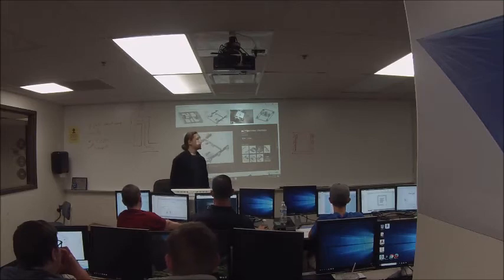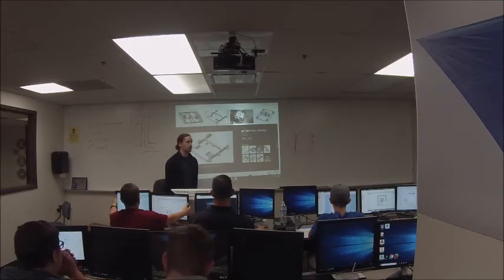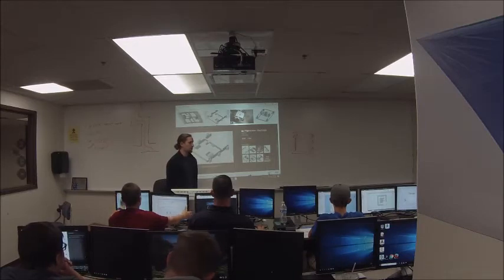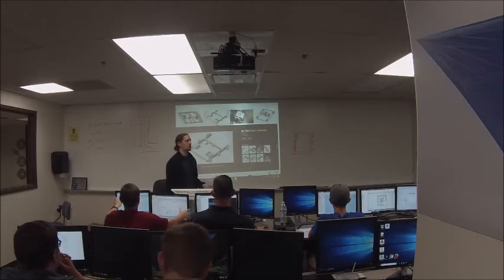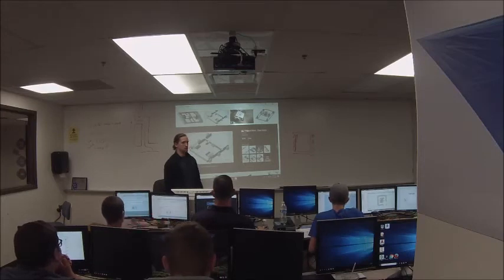So at the beginning of the build season, we're going to have a discussion where we're going to talk about what kind of drivetrain we want. Now obviously the most common is a tank drivetrain. That's what we've always done in the past, but there are other options out there. We'll weigh the pros and cons, and if the game calls for something else, that's what we'll do.